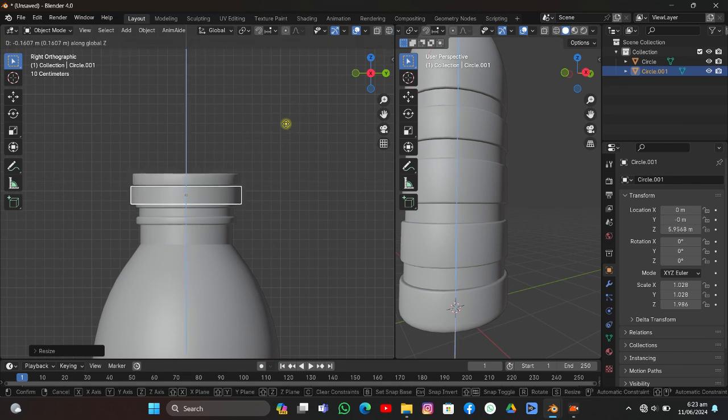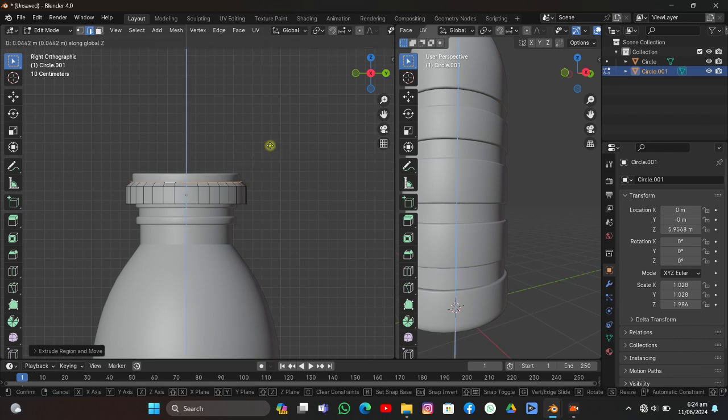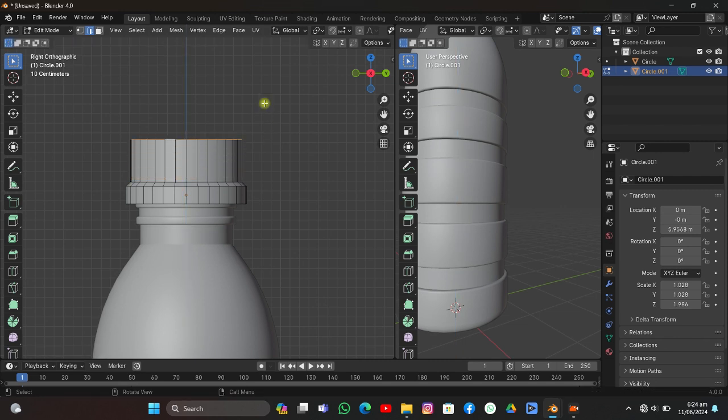And if I just get it down like that, and if I go to edit mode, I'm going to select edges like that. I'm gonna scale it like that. I'm gonna select these edges. I'm gonna hit E, extrude it downward by hitting S again. I'm gonna move it up on Z-axis. I'm gonna hit E, extrude like that, and we have something called piston.